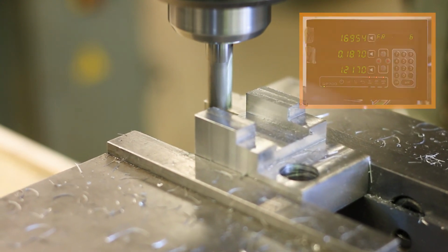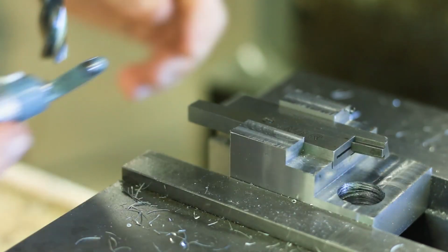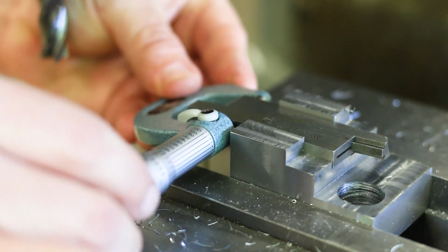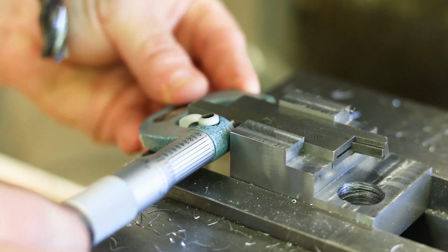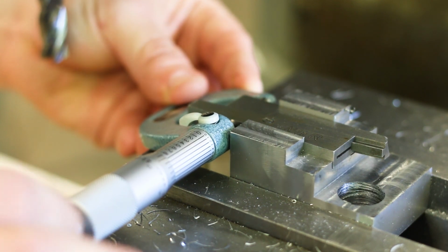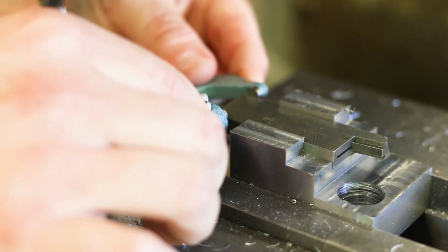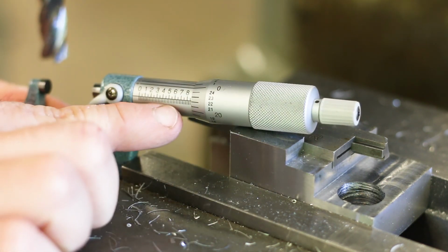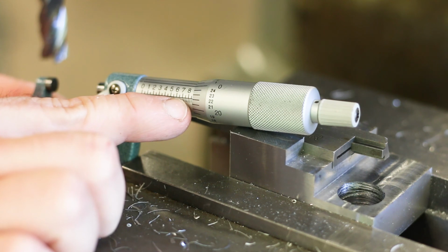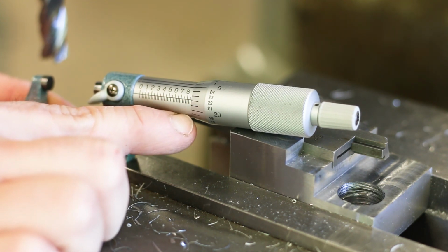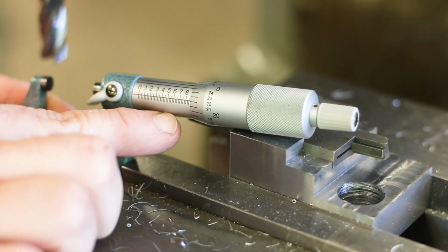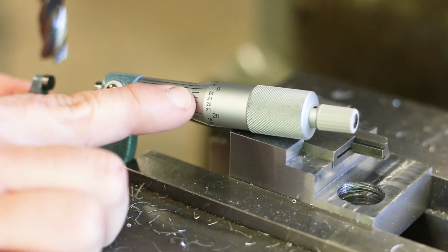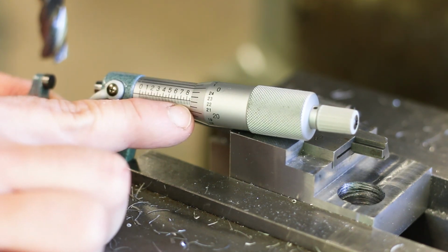Absolutely gorgeous. Okay, go ahead and put the adjustable parallel in there and open it up. Let's go in there with the outside micrometer and measure over top of the parallel. Okay, let's see what we've got. It says 850 plus 22 and a little change. So 850 plus 22, 872 and a little bit. The target was 875 plus or minus 5, so we're definitely inside of that range.